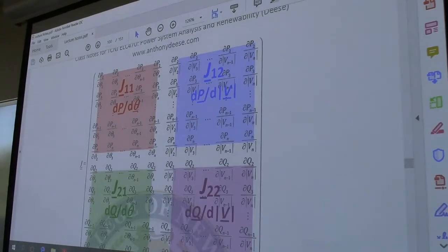Now when you look at the size of this system, this is beyond what we would probably do in this class. Forget about the n for a second. Just imagine it being an 8 by 8 Jacobian matrix. Okay, so that would be the equivalent of a 5-bus system, right? Because the infinite bus is not going to be represented, and so you have 4 thetas and 4 voltage magnitudes, which means 4 buses. So that's a pretty big system, especially for our purposes.